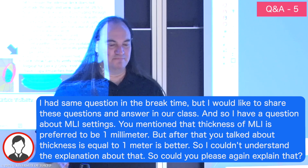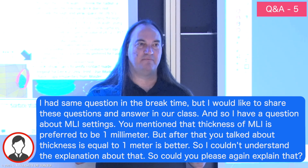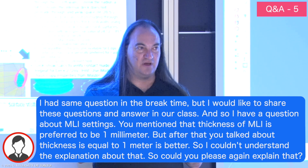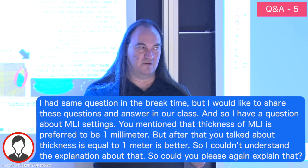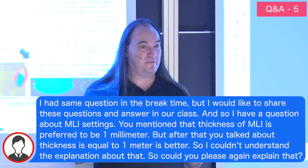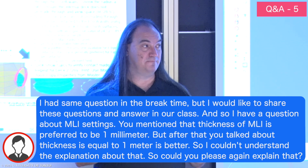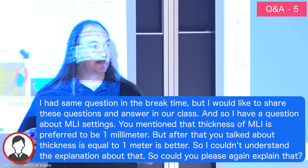So if I want to get the area of the MLI, I would have to manually click points and say, what's the area of this? But if I take the volume of the MLI, which will be based on the geometric area that it has, times that thickness parameter, I can take the volume multiplied by a density to get a mass.